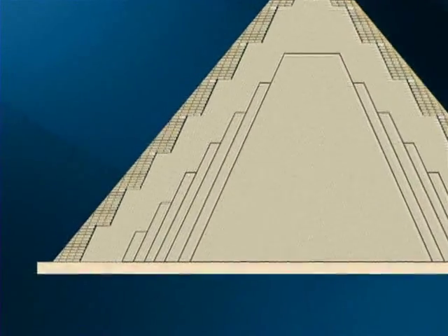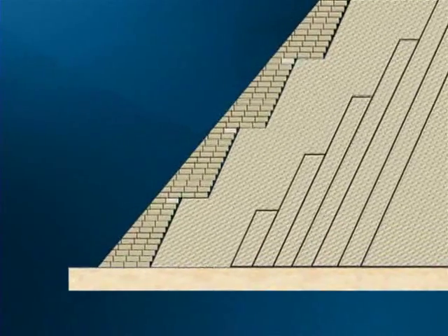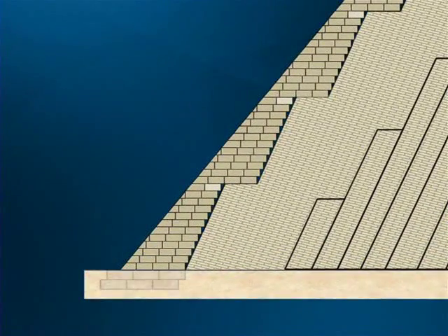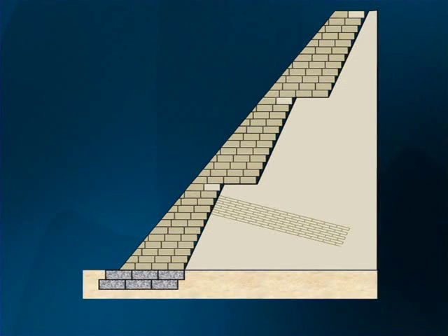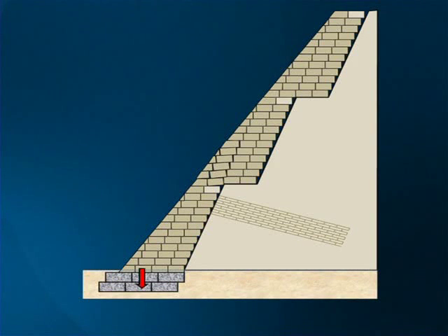Mendelssohn's investigation showed that when the outer casing was added to the step pyramid, it was placed on its own foundation, composed of large stones that were placed directly on desert sand rather than on bedrock. It was built with horizontal layers of masonry, in contrast to the inner core of the pyramid, where the masonry layers are sloped inward to improve their stability. So, it's very likely that the casing foundation settled because it was resting on sand.